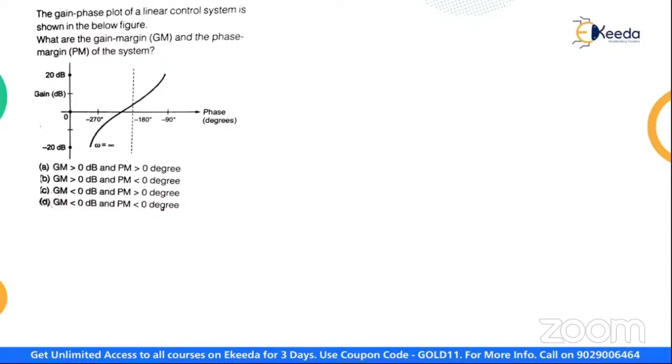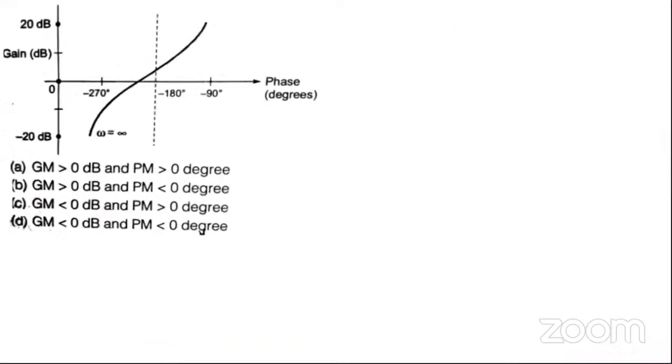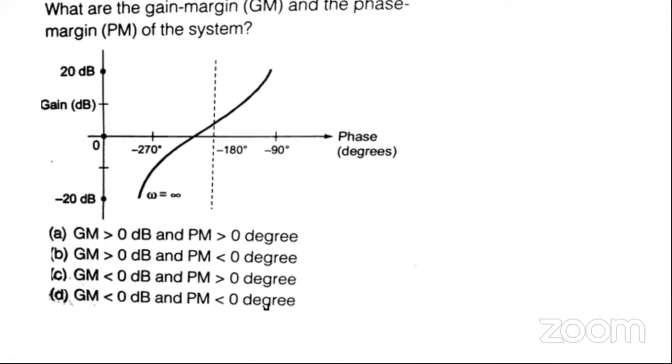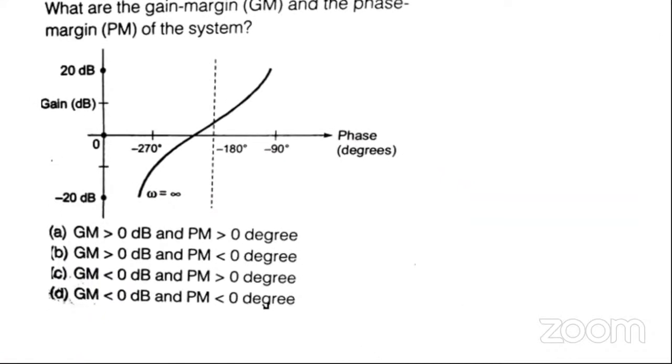Okay. So let us see what is gain margin and phase margin. Let us do the manipulations here only. See here. We can zoom. Whenever your gain plot reaches 0 dB, this is your omega GC. Let me draw one line here. This is your omega GC. What is this value? This is your PM, which is phase margin.